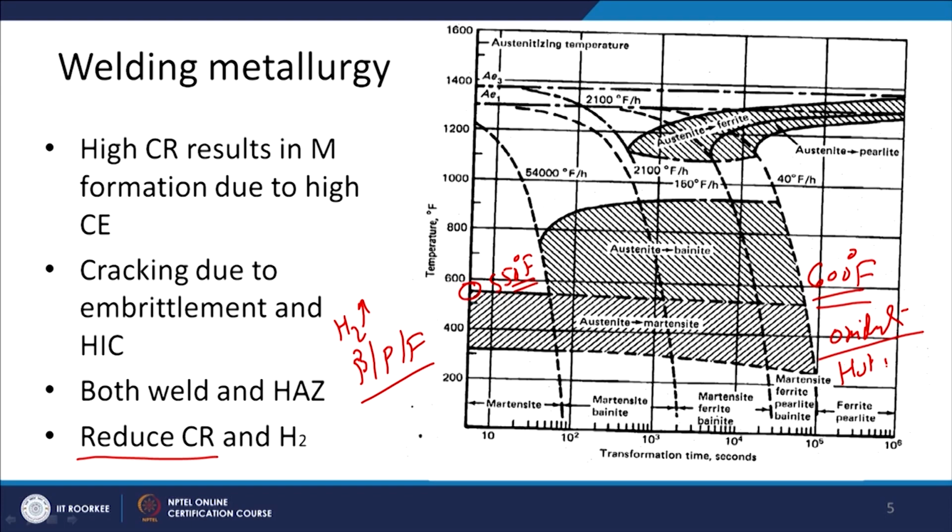So, working with the hot plates during the welding as well as oxidation tendency, these are the two adverse effects which are associated with the higher degree of preheat, although it will help in reducing the cooling rate and it will also help in reducing the hydrogen content as well as the formation of the martensite. It will reduce the hydrogen. So, the cracking tendency will be reduced, but it will make the welding difficult due to the dealing with the hot plates as well as the due to the formation of oxides by the steel plates when they are heated to the high temperature during the welding.